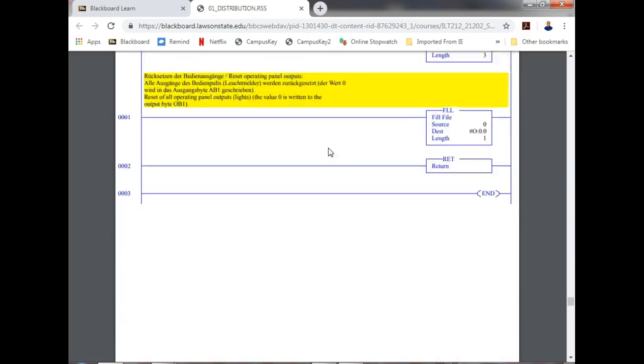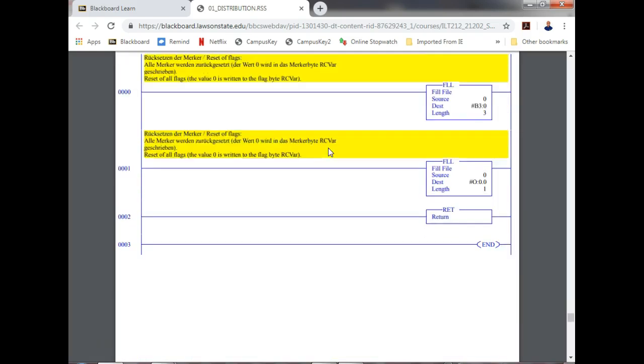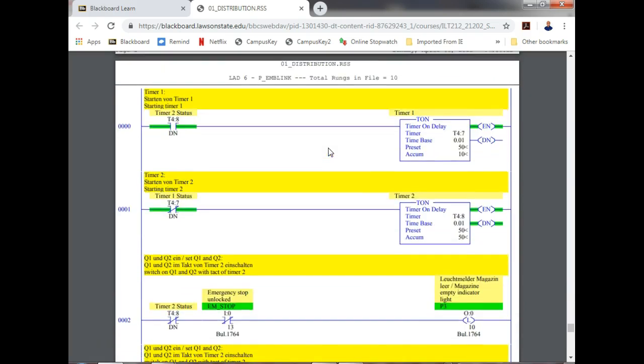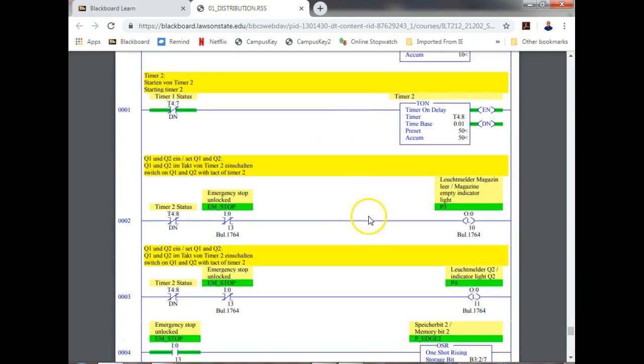Back here on the emergency stop, we're going to change this up. It uses cross-coupled timers to cause the lights to flash. We're going to use the timing bit, and I'll show y'all that and where you can pick that up in the Allen Bradley software. So we'll use that back here, and then